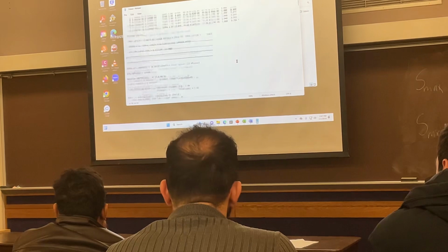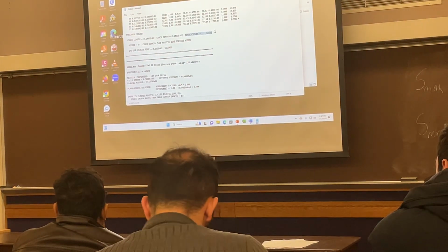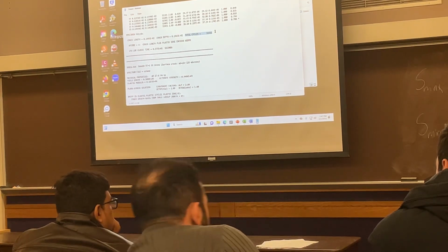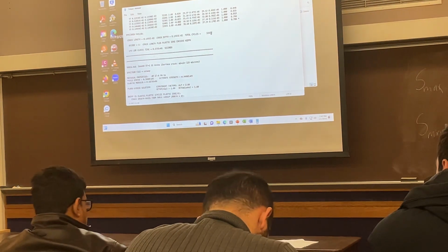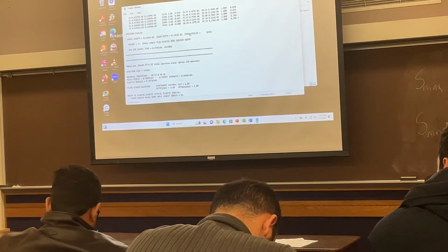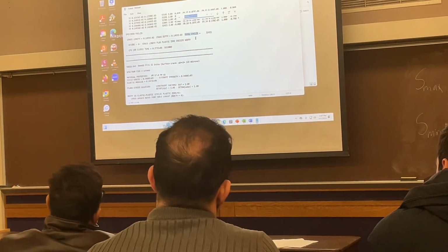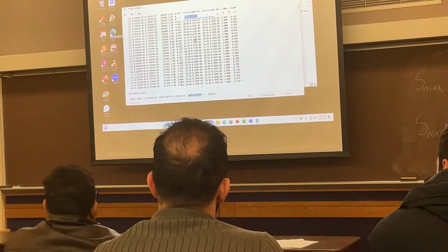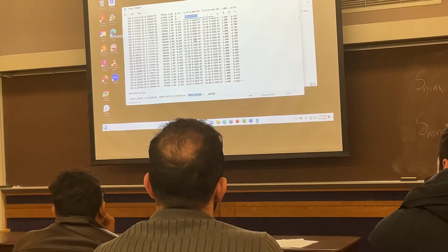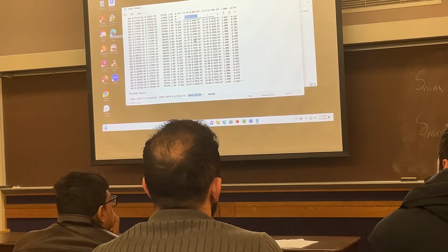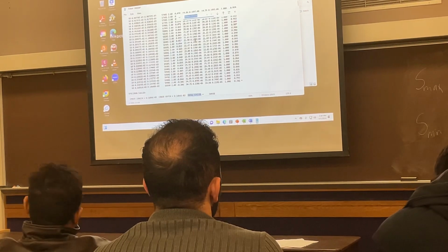At the end of the number of cycles to failure, you see the total cycle. This is what you need to get from your output file to put in the table. So you define the stress level, and based on that stress level, it gives you the total cycle. An easier way is just to search the total cycle in your file. So 2, 3, 4, 5, depending on the number of stress levels that you define, you can quickly find that. That's the only thing that you need to get from the output file, just the total cycles, and just search.